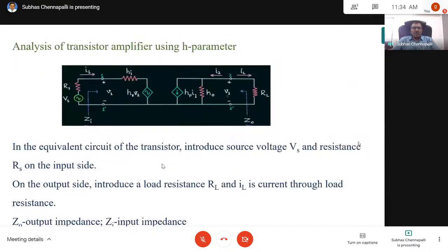And even we work out on simple H parameter model also. How it is done, I'll show it later. Simpler model than H parameter. That is also, I can say, approximate H parameter model. When you apply that model and calculate all the 6 parameters, we calculate the error because of simplification of the model, compare that with full model, H parameter model. If the error is limited based on the application, suppose application can take error of say something like 5%, and the error is less than 5%, you can always accept it.